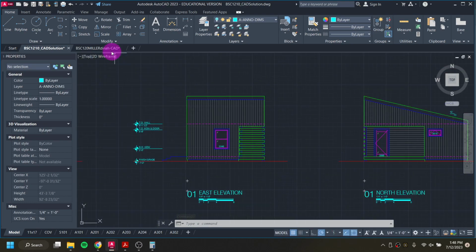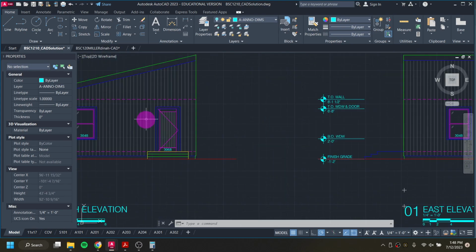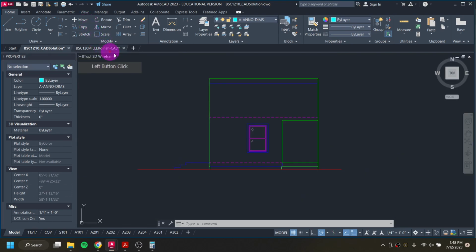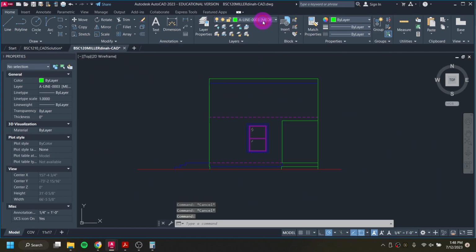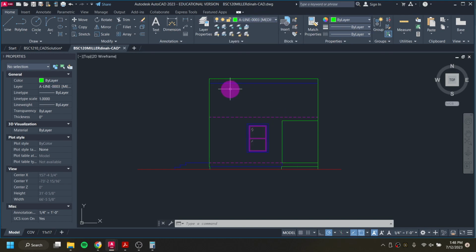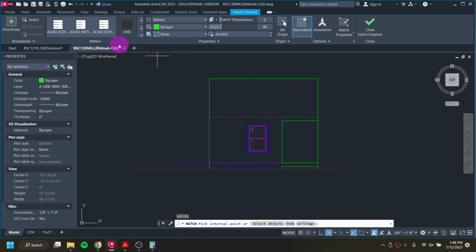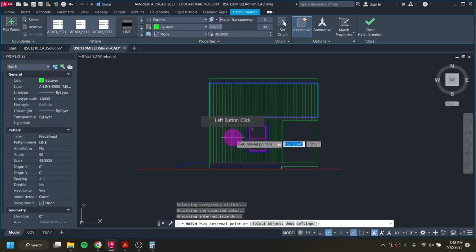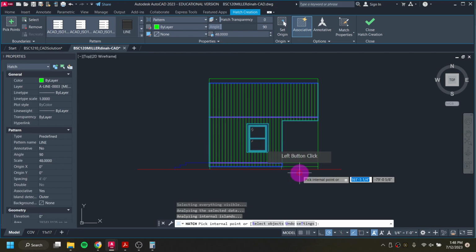So this hatch is going to follow the exact same pattern that this hatch followed. And so for that, I'm going to switch myself over to the pat layer. But let's say, for fun, I didn't. Let's say I kept myself in this medium one, and I started the hatch tool. Hatch recognized the last time I used it, I used line. It recognized the angle and the scale, so I don't have to change anything. But I go to hatch these 3 areas, and I realize, oh no, I'm in the wrong layer.